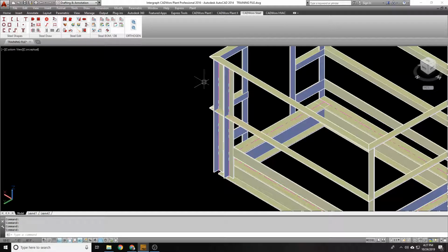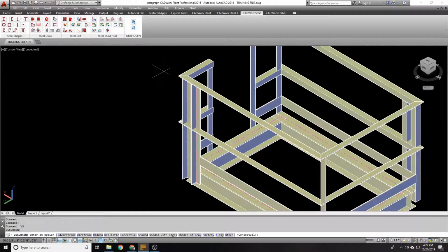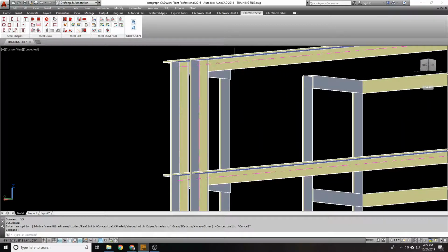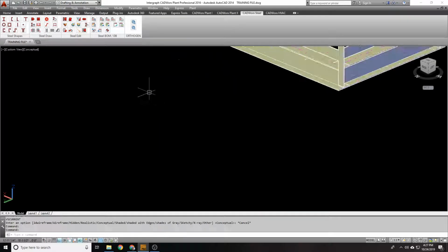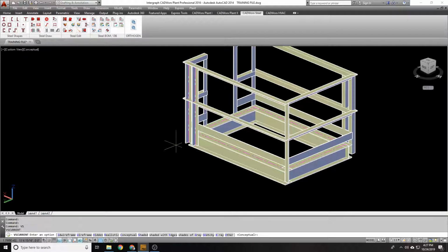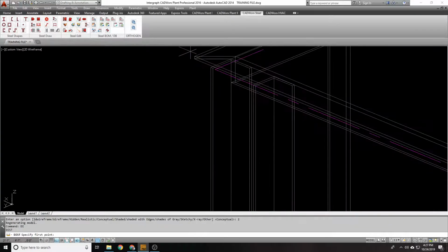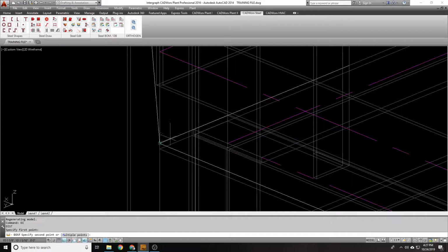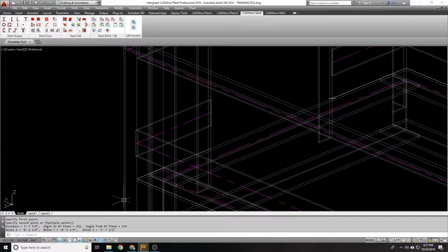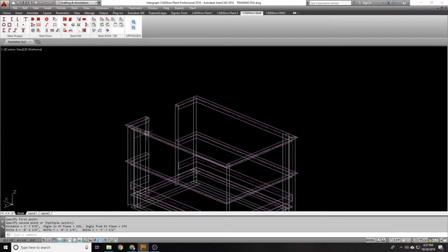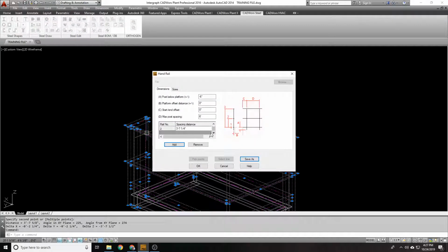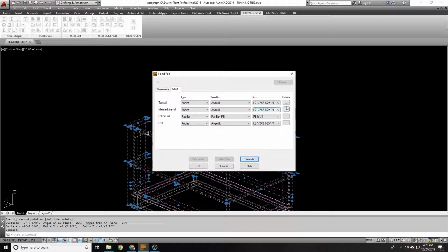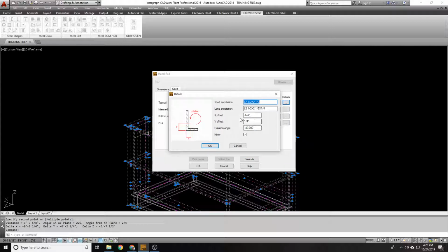All right, now time for that measurement. Now we put it at 3'7" and 1/4. For angle, it should be on top, but we do have a center line set right here. So let's give it a dimension. Let's measure from here down to here, and we're at 3'7½". And we set this at 3'7" and 1/4. The reason you're probably seeing that 3'7½" is basically because of this top rail getting a 1/4 inch offset.